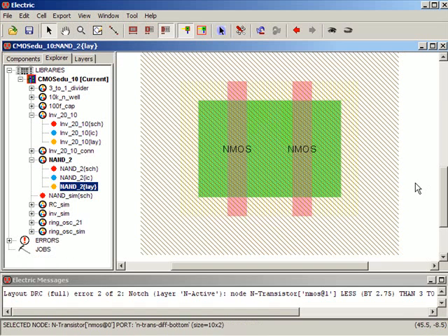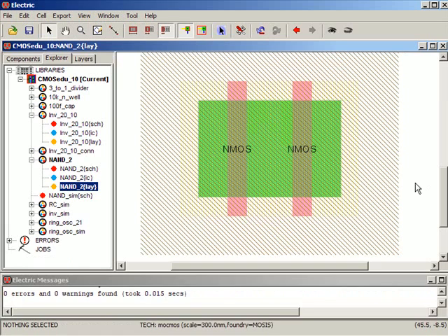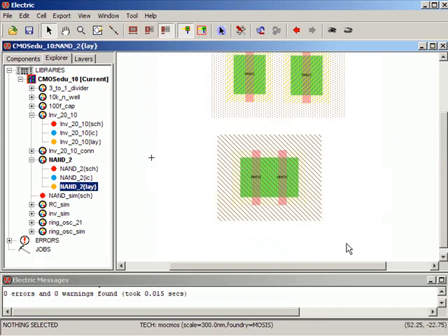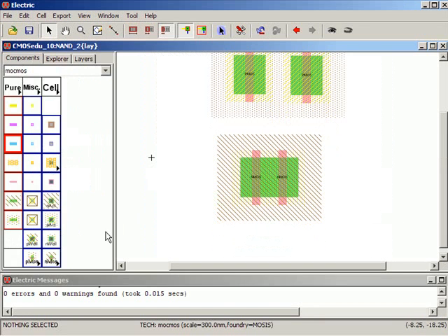Pull it over a little more. Hit F5. Alright. So my selects overlap and I've got my 2 transistors in series. Now I need to connect one side to ground of the transistors, so I'm going to go ahead and put down this is the P well, and of course if we're not using the P well we still draw it just to make our layouts more generic.